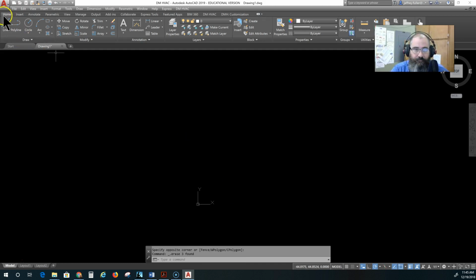So if I'm drawing a line, and it says specify first point, and you see in the dynamic input boxes out to the right, it says 8.805 and then 6.7215. That is your XY coordinates. You can type in coordinates and go to a specific coordinate, but you don't have to do that. What it's referencing right now is that home point right there between X, Y. It is referencing that point.